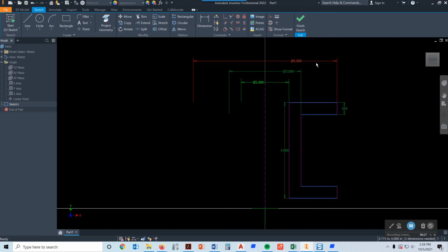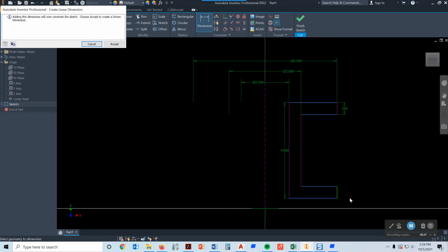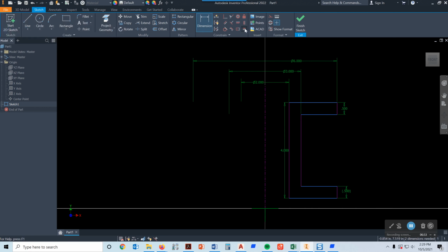All right. So those are those diameters I was showing you earlier in the sketch. And so when we go in here and do the revolve command with this profile right here, we're going to end up with all these diameters in there. Now, if you want to put a dimension and check this line right here, it's going to tell you it's over constrained. So that's going to be 0.50, because if you remember earlier, I used the equal constraint, and I said I want this line to equal this line, and I'd already put in a dimension right there. So I'm going to press escape, drag this out here if I can, so put the 4 out there.